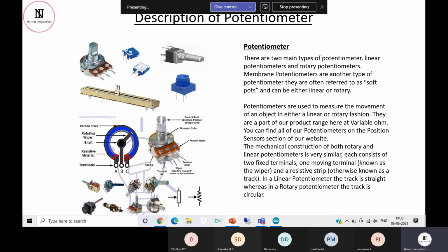Fine. So this is the basic symbol of how a potentiometer looks, and we have three terminals for the potentiometer. The leftmost end and the rightmost end will be used for the power supply. You can use either one for the 5 volt supply or the ground supply. Since it's a resistor, it is providing resistance, so the connection side does not matter that much.